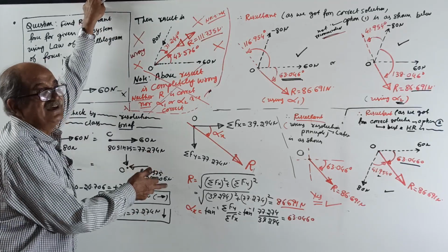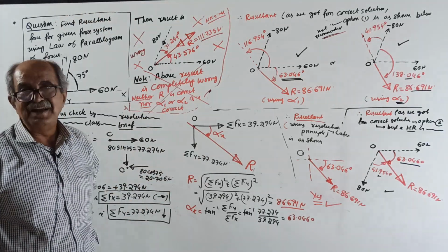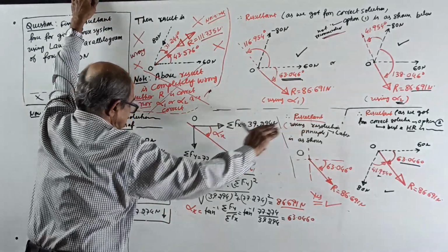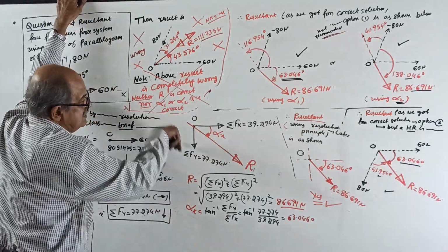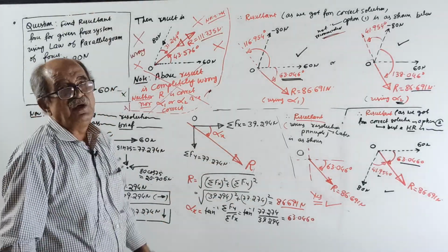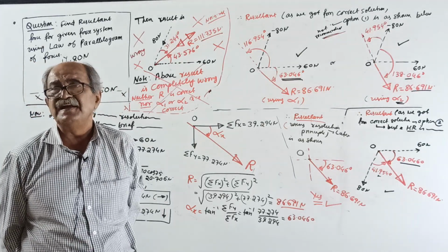If I am doing personal calculation, first of all, I won't write anything. Okay, start. Now, sigma Fx is right side, sigma Fy is down, resultant this way. Remember, resultant equals root of P1 square plus P2 square plus 2 P1 P2 cos theta, same formula, cos theta with theta 90 degrees.